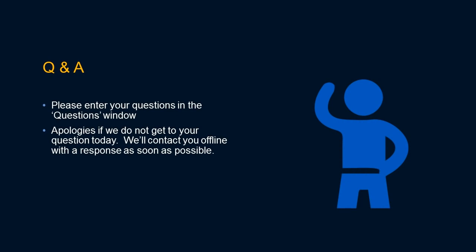Gotta love the marketing. Here's a good question from Vincent. He says, does the master count as one of your devices? So can you have one master? The master does. Of the 247? So, yep. So you can really have one master device and 246 slave devices because everything's got to be uniquely addressed, and the master includes that. Because if you think about it, the master is going to need to know if the data being sent up by a slave is meant for it. That will almost always be the case, but it's good to have that confirmation in there. So the master is uniquely identified by an address.